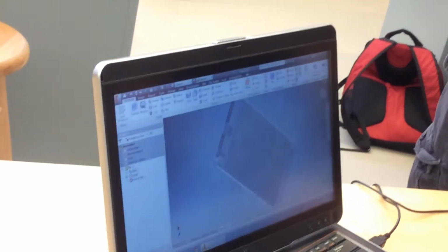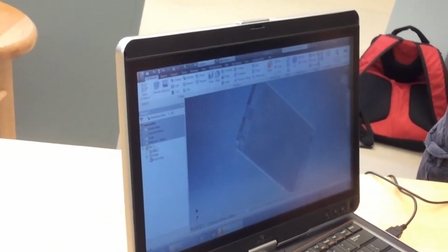Now, remember, start on the back of the phone so you're all starting in the same spot. So I'm going to click here to start the file on the back of the phone. Now, notice that I go into this File 1 here. I'm no longer in assembly. I go into this part file, and I'm building the part file off of this reference file. So now it's a reference of it.